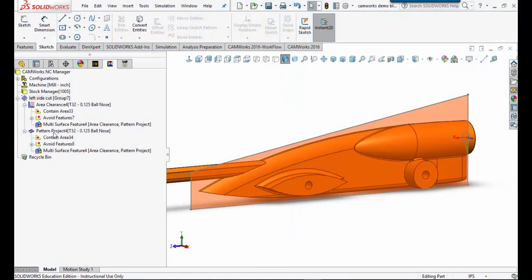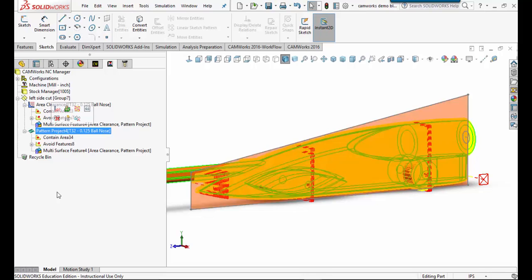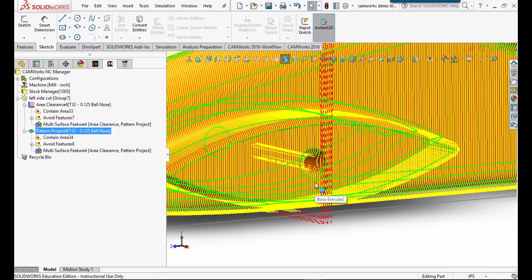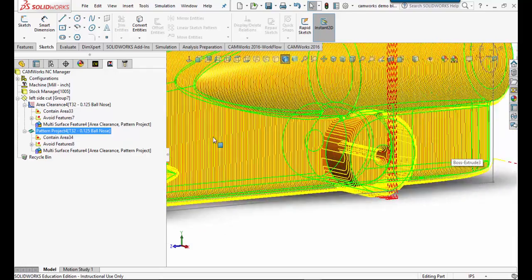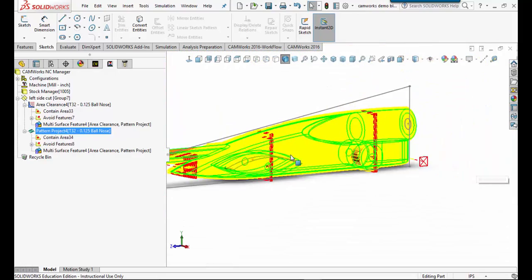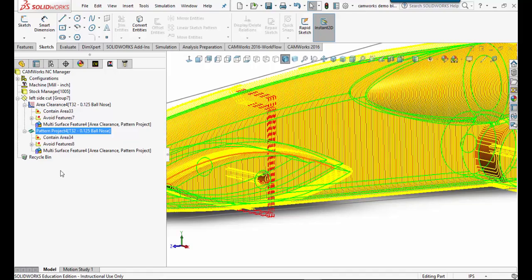Okay, now that we've got our fine mill path set up and it looks great, and that's what we want, what we need to do now, if you notice in that fine mill path, it comes in and tries to mill out a hole. Well, that's pretty normal, because it's looking at all the features that are out there and it's going to immediately try to make that plunge.